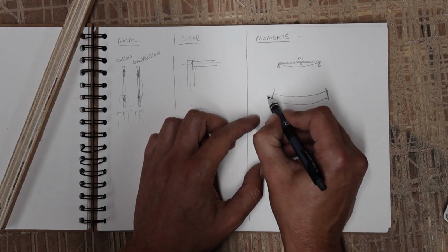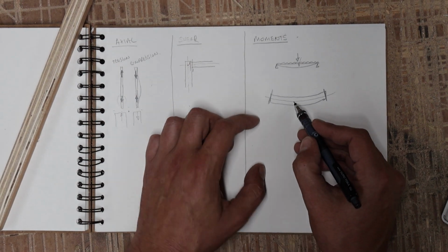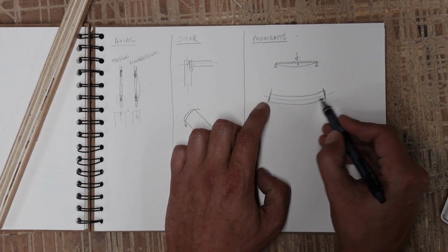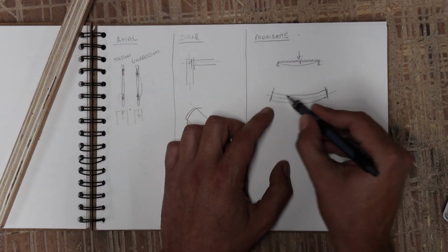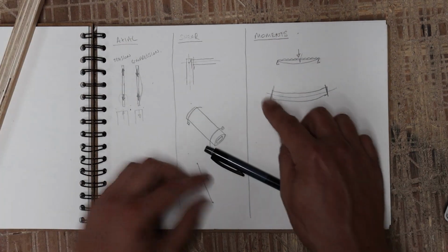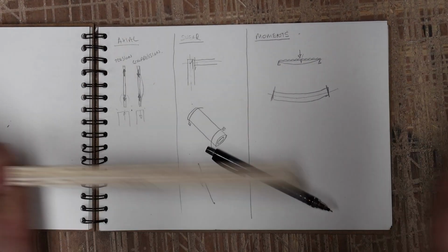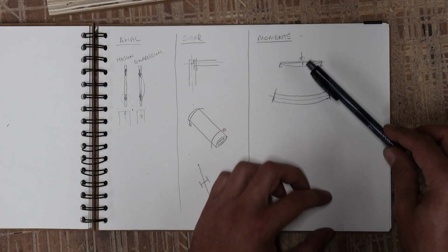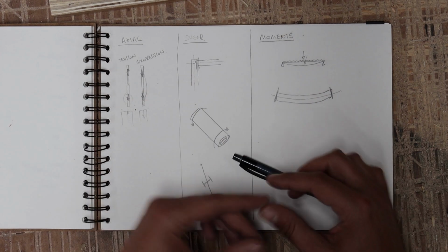And if we draw a center line along the material, along the beam, then that is exactly the same length that it started out. It's the center. So by logical extension, because this has got shorter, the only way that happens is if it's in compression. This bottom surface has got longer, so it's in tension. So bending moments are technically a combination of these two working in conjunction with each other.